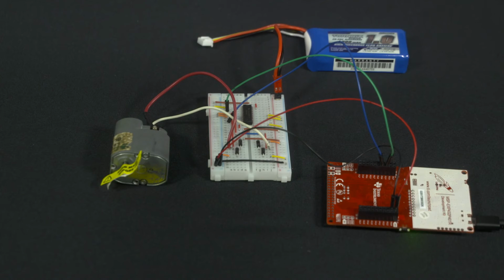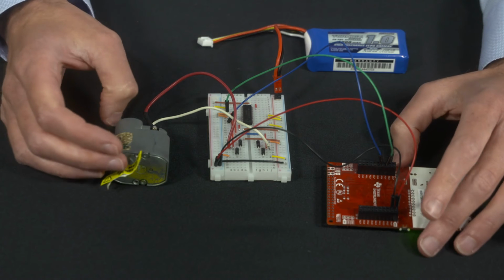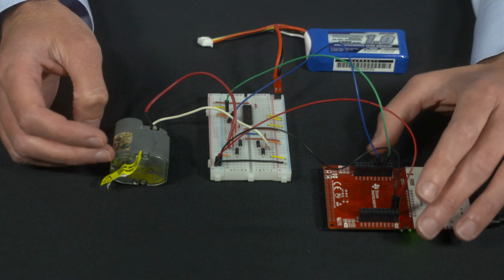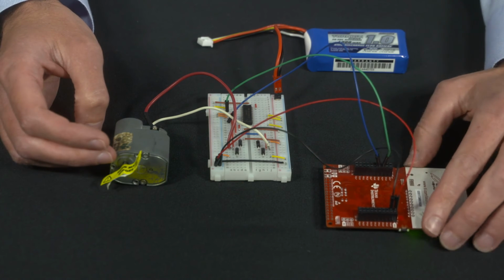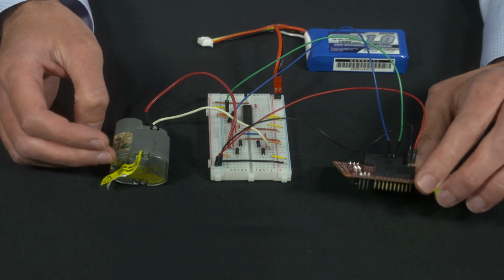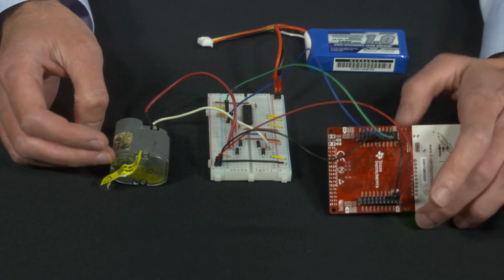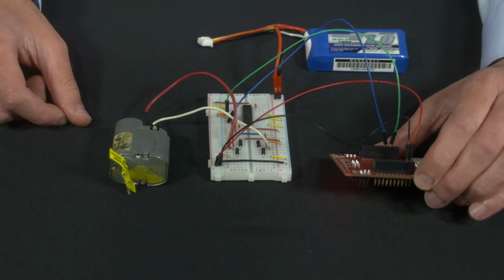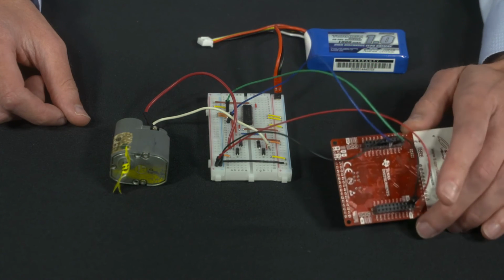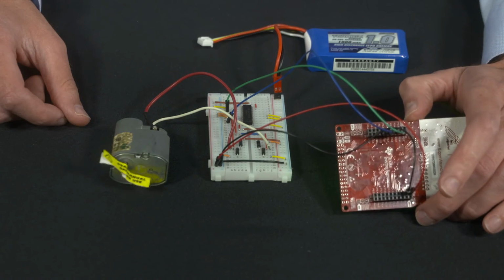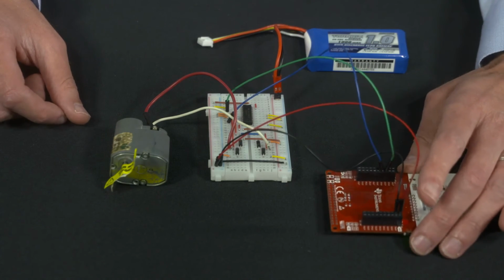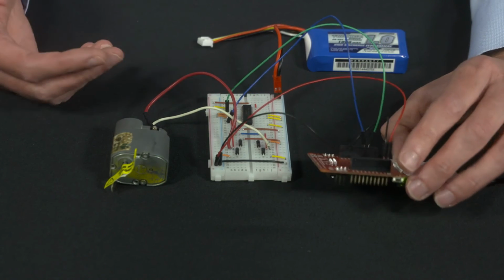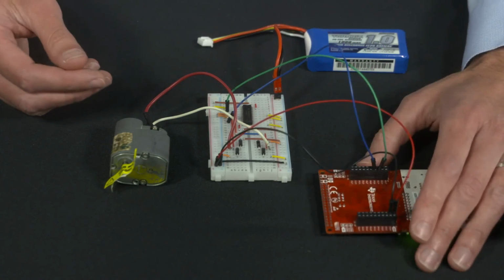As the final part of this demo, let's take a look and watch this circuit work. So we've uploaded our code that we just saw onto our microcontroller. And now all we have to do is press one of these buttons here, either the front button or the back button here, and we'll see the motor turn in different directions. So let's press the first button and we see the motor rotating. We push it again and it stops. And then we press the button on the other side of the microcontroller, we see the motor rotate in the other direction. So this is a simple H-bridge setup that allows us to turn the motor on in either direction with digital logic and just using these buttons as inputs.